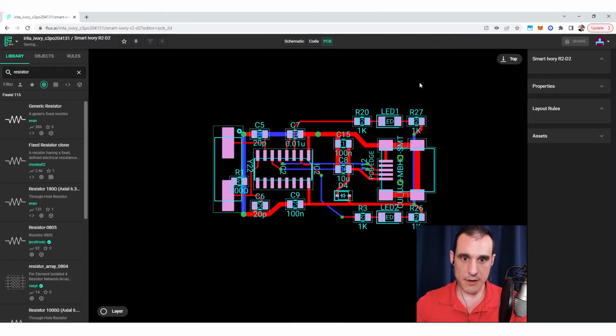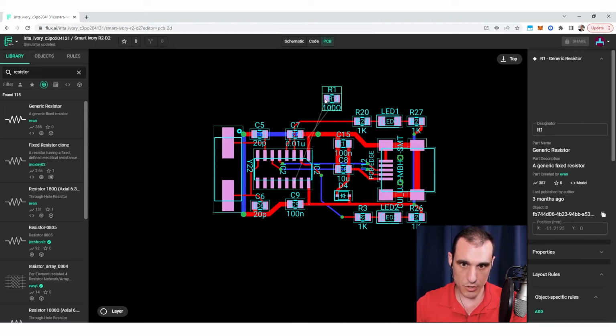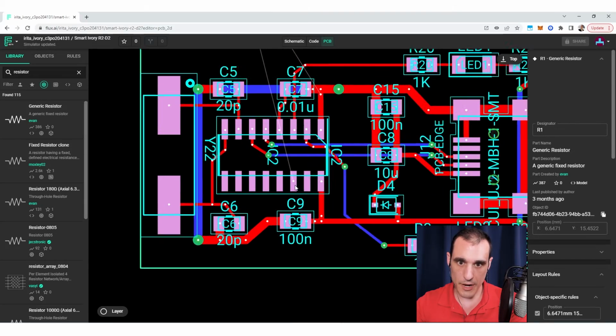So once I place that resistor, move over to the PCB layout, you can see here that this resistor has to make two connections, right? One is on the outside or near the outside of the sublayout region, but the other is one of these pins coming directly off the integrated circuit. And so you can see that right here.